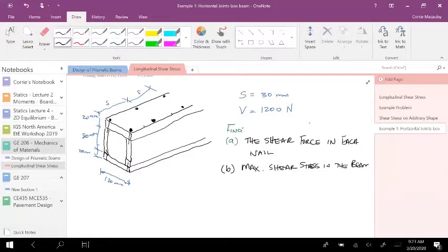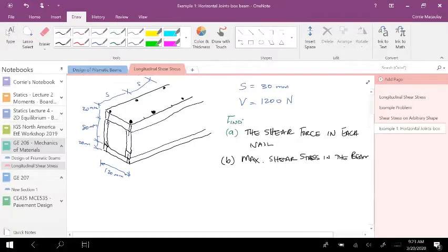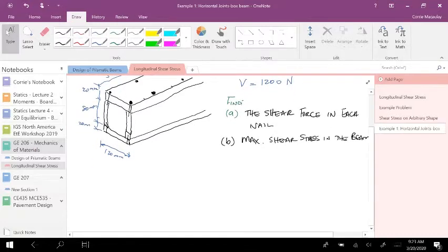If you're looking for shear stress, right? But the first thing that they actually ask us to do is shear force. So basically that's that delta H, right? But we're still going to need I. We're still going to need Q. So let's see if we can determine I for this cross section here. I would be equal to, anybody want to tell me how can I calculate I for a hollow section like that?